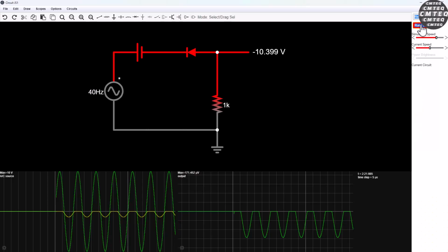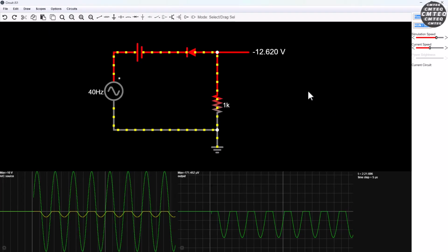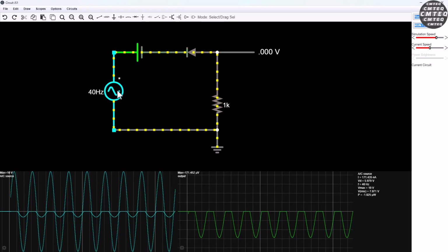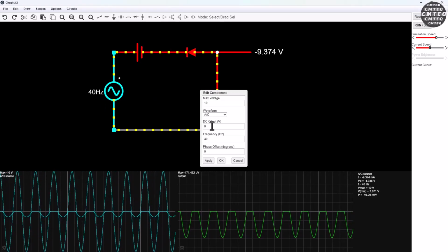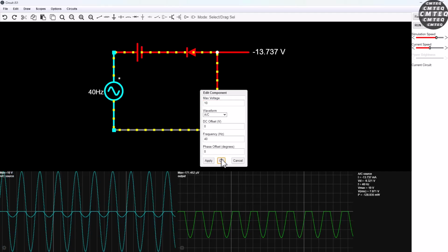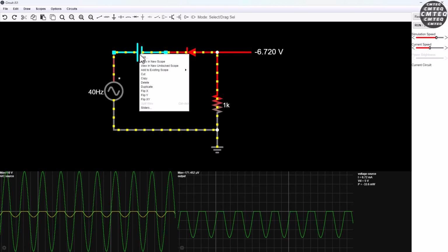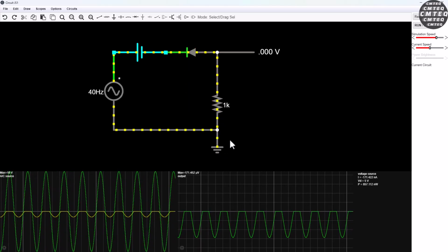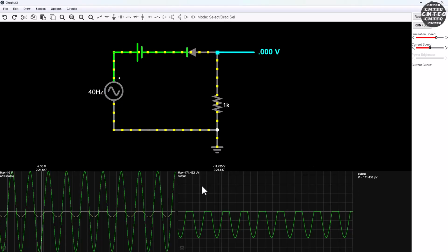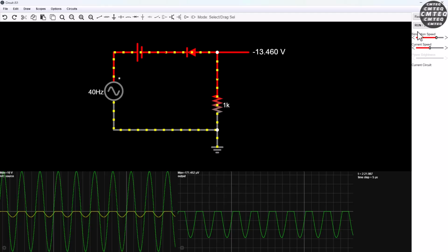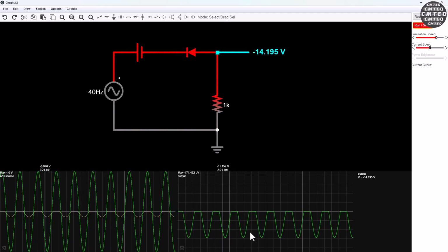And if I may just run this simulation here from the applet circuit simulation. So I've got my input source here, which is an AC signal with an amplitude of 10 volt. I've got a normal silicon diode here, and I've got my voltage source set at 5 volt. Now as you can see, the output waveform is basically exactly as we've seen in the previous slide. If I stop this here, you can see the magnitude of the negative peak is 14.3.